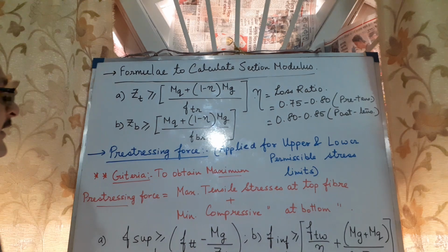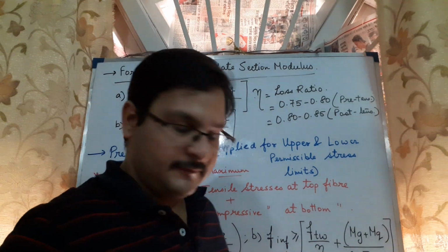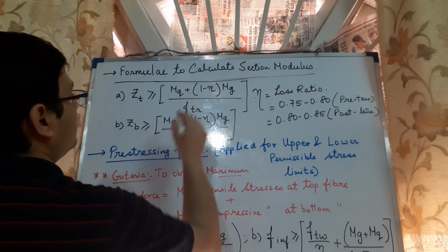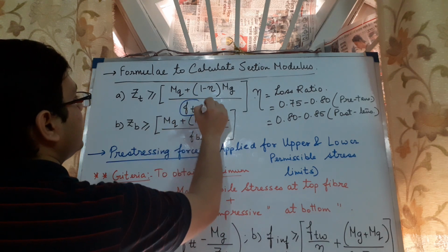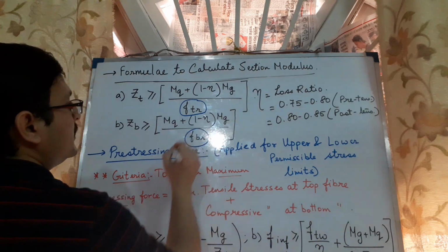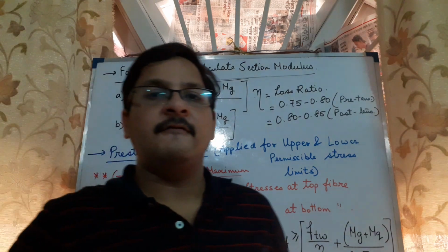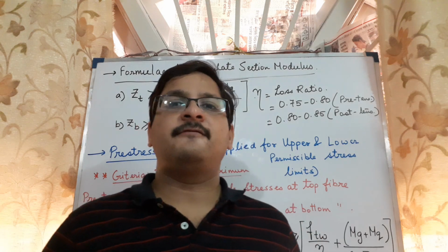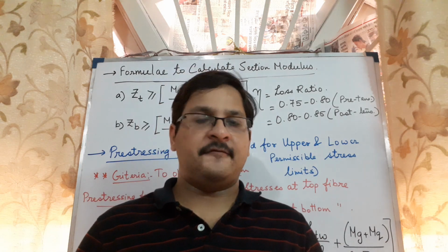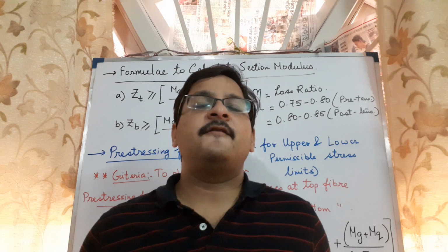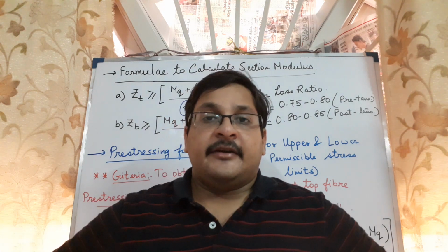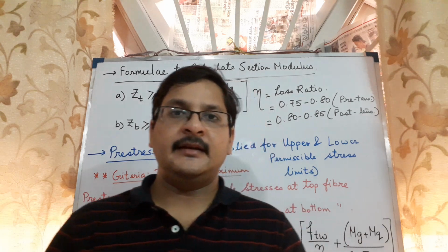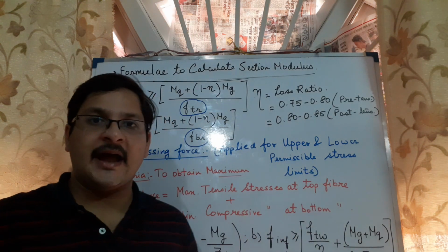Now obviously there is another thing which I wanted to mention, that is we have these FTR and FBR. So also we have another separate set of two equations, one for FTR and one for FBR. FTR will represent the range of stresses at top. FBR will represent range of stresses at the bottom.